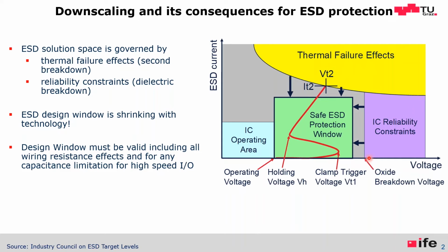The other issue is the metallization. The metallization gets thinner and smaller, which is fine for the digital signal, but it's not fine for ESD. You need many contacts and a lot of area and metallization to carry the current. The consequence is that the cost per IC which is put into ESD protection will go up the smaller the structures are on the IC.